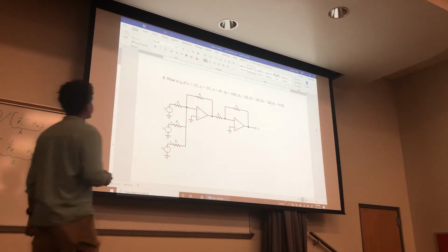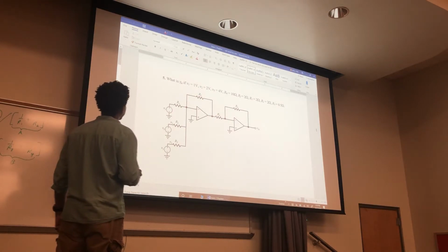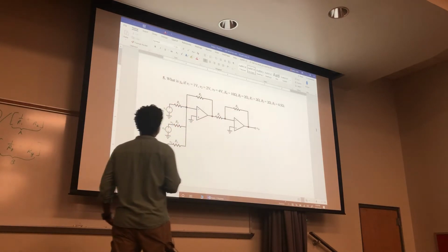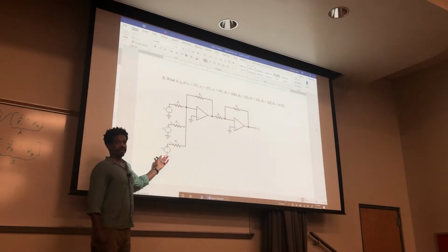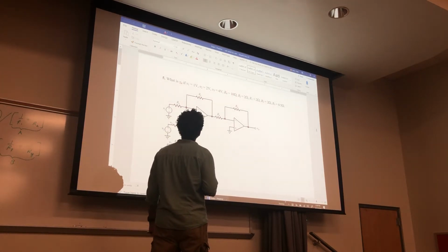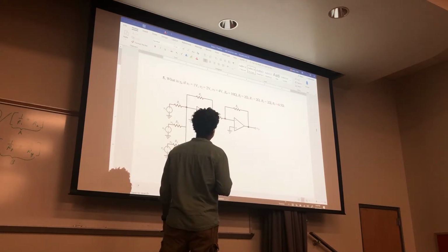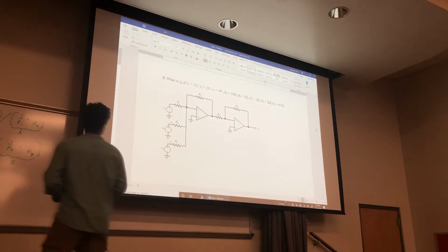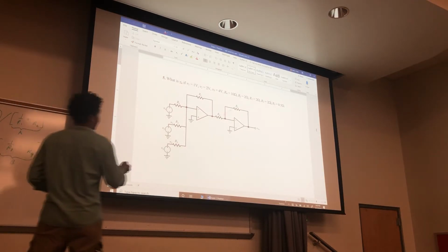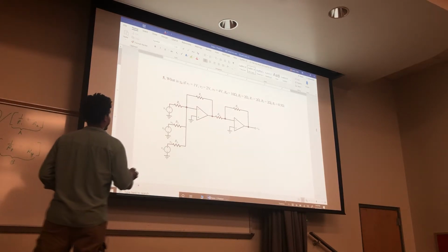Okay, so what is V out? If V1 is 1 volt, V2 is 2 volts, V3 is 4 volts, here are those right here. What kind of op amp is this? Yep, summer, exactly. R4 is 10, RF is 2, R1 is 2, R2 is 2, and R3 is 0.5 ohms. Okay, what is this? And look, it has an R4 and R4. So that's nice.